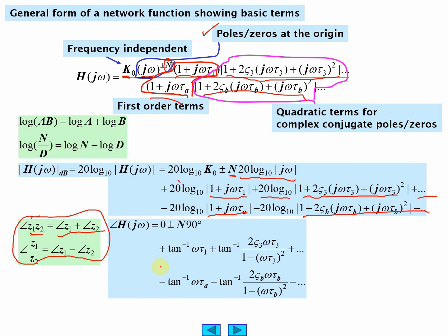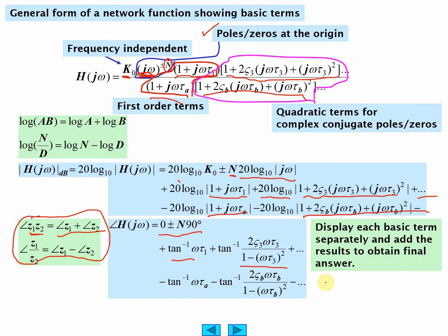So we can get the same kind of idea here. Excuse me, this is purely plus or minus 90 degrees. And if it's negative, it's capacitive. If it's positive, it's inductive. And then all these tangents, tangent of all the imaginary parts divided by the real parts, and so on. It keeps going to infinity and beyond. If it doesn't go to infinity, real networks have a limited amount. We do go to infinity when you're analyzing a cable, for example.